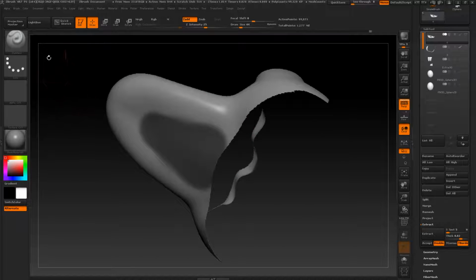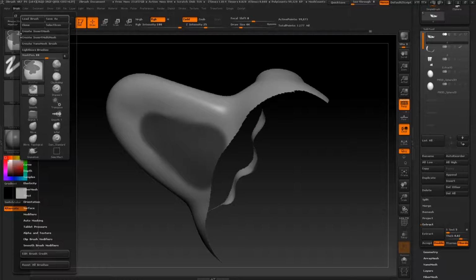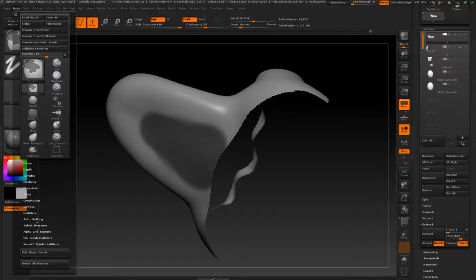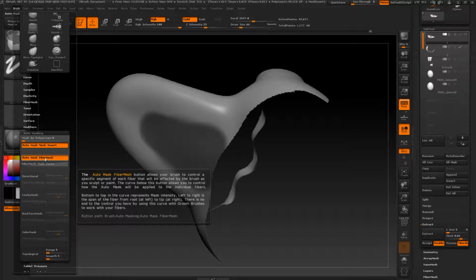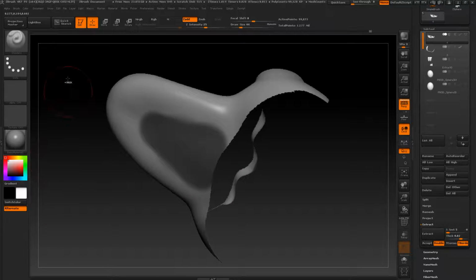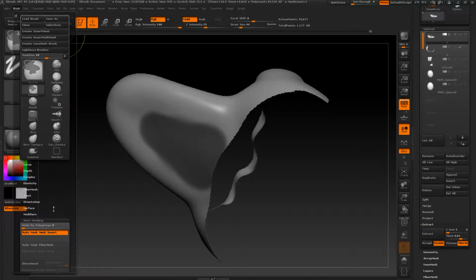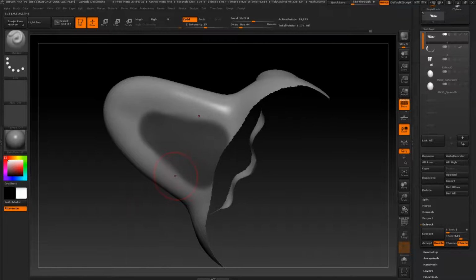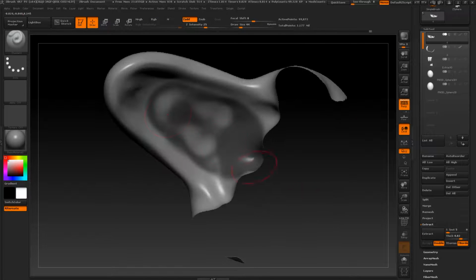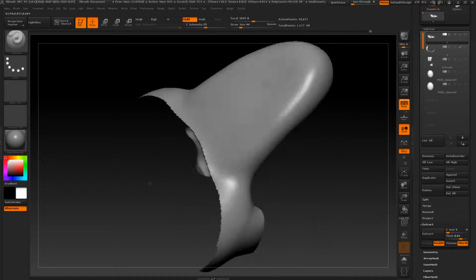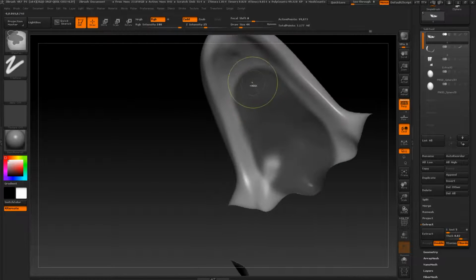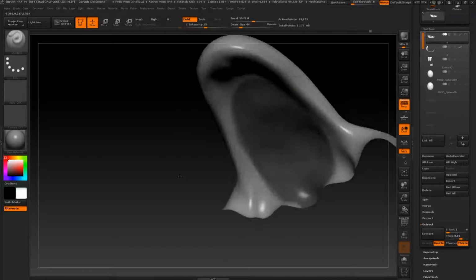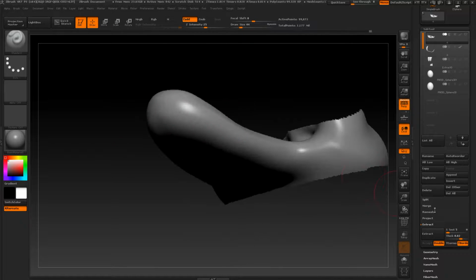As you can see, we have our mask in the bottom also, so we need to press Ctrl, go to brush, auto masking, and uncheck auto mask fiber mesh. Okay, now if we press Ctrl Alt, we can unmask this one, but we should have over here, but still do not. I don't know why. Maybe it's too... okay. Now we are good.